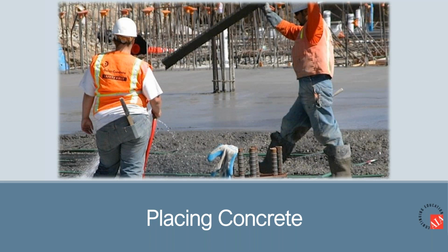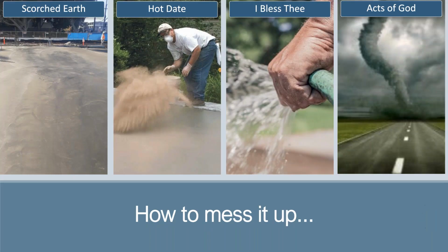I no longer have the ability to control my water cement ratio. I don't know what they're doing. I don't know if they're spraying the dirt. I don't know if they're spraying the concrete. I have no idea. Don't add water at the site. It's very critical that we control every step. We spent a lot of time and money developing a spec. Minimize the chances of risk.